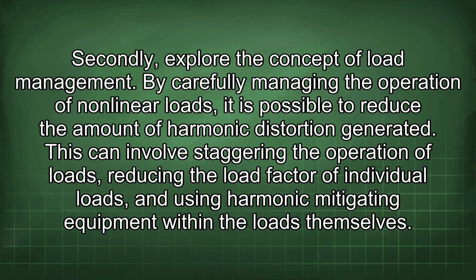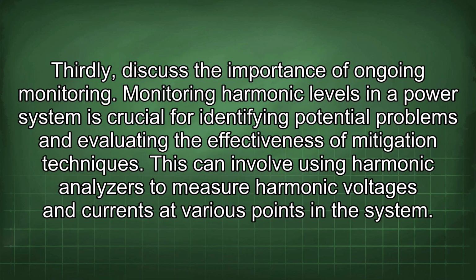Secondly, explore the concept of load management. By carefully managing the operation of nonlinear loads, it is possible to reduce the amount of harmonic distortion generated. This can involve staggering the operation of loads, reducing the load factor of individual loads, and using harmonic mitigating equipment within the loads themselves.